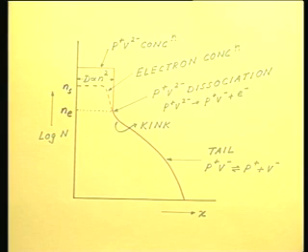So, that is what I have also shown here, that in this flat topped region D is proportional to n square. And since D is proportional to n square, this is going to be really very abrupt. Over this depth, there is hardly going to be a change from the surface concentration, it is going to be truly box like, and then it starts to fall abruptly, very steeply, right.